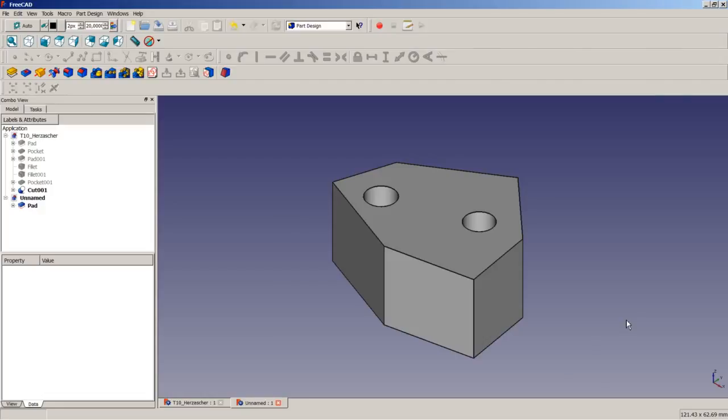What's the story about the sketcher and the solver now? Well, the solver is running constantly in the background and taking into account all manually and automatically set constraints in the sketch. And the solver is trying constantly to find a valid solution. And of course, the solver is reporting back constantly its findings, if everything is okay or if we have a problem.